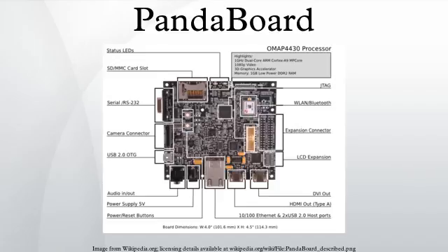The board can output video signals via DVI and HDMI interfaces. It also has 3.5 mm audio connectors. It has 2 USB host ports and 1 USB on-the-go port, supporting USB 2.0.